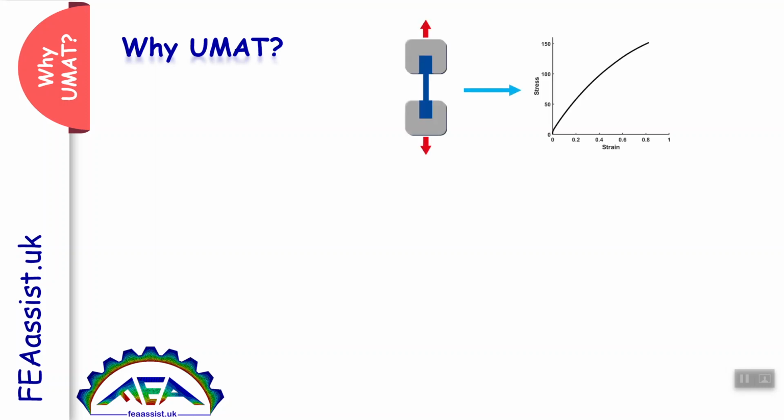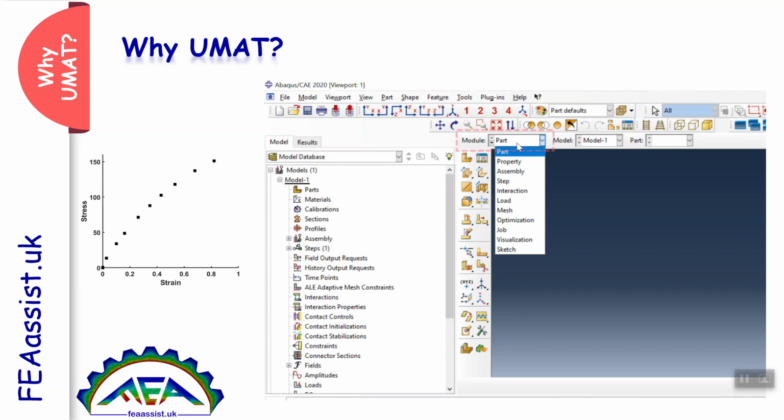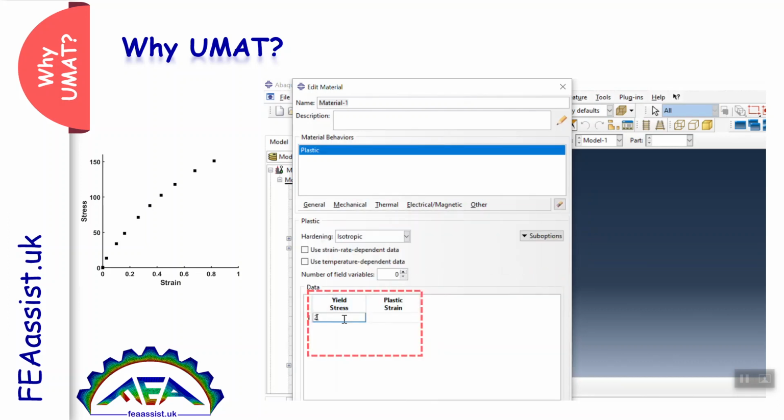Consider you have a sample and you want to apply load and, by modeling and simulating, predict the mechanical response of this sample, predicting the stress strain curve. The first strategy is that you have some of the points of your stress strain behavior from lab or from published experiments. You can easily go to Abaqus, to the property, define a new mechanical behavior, plastic behavior, and enter those points like this.